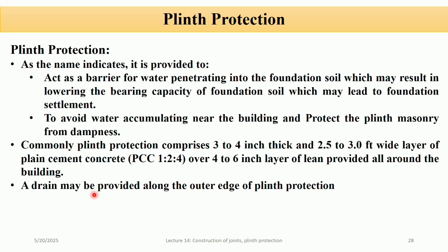A drain may be provided along the outer edge of plinth protection. So plinth protection is a concrete layer around the base of the building that prevents water from damaging the foundation soil and plinth masonry by stopping water infiltration and directing surface water away from the building.